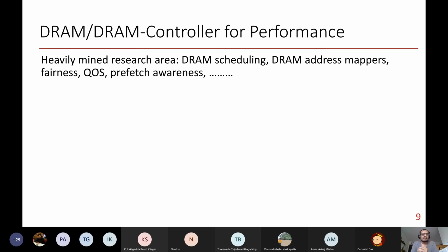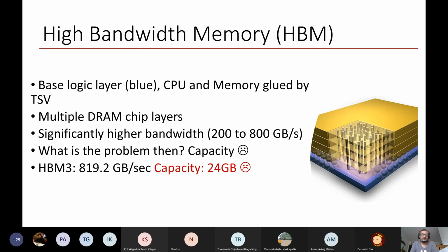So there, scheduling is still a major bottleneck, and it is still an open problem. It's not solved. It's just that the community has moved away thanks to HBM. Every time you now write something about bandwidth, they say, okay, go for HBM. Why improve the bandwidth of DDR? So these are the different trade-offs.